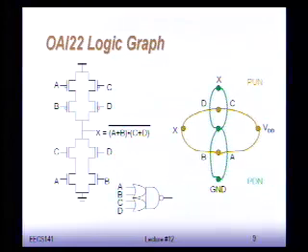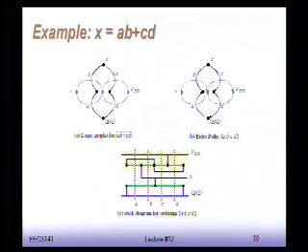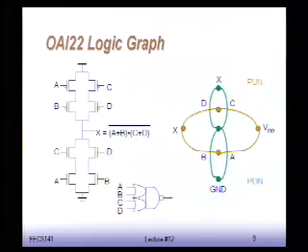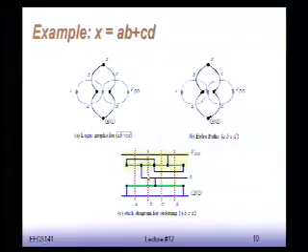So you can do this for more complicated examples, like this AOI. So this is an AND-OR-invert 22 gate. Again, you can derive what the Euler paths are and then turn it into a stick diagram. And you can see that for these complex gates, working out the possibilities by hand is not trivial. And therefore, it's useful to have this automatic tool that spits out this layout without you doing almost any work. Okay.